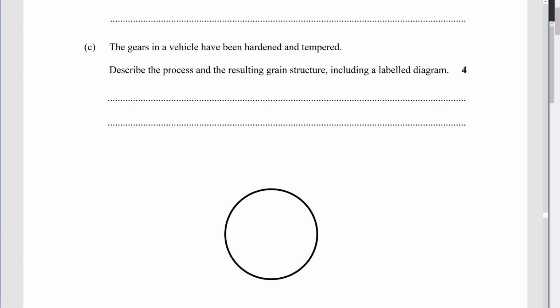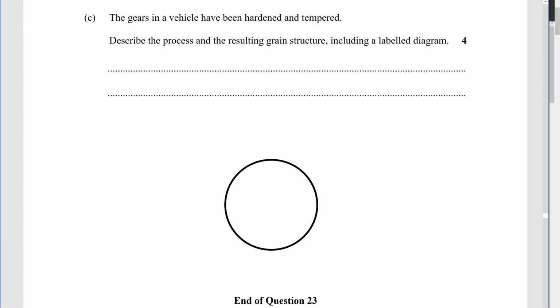Now, when I've had this question in the past, people have said, what's the difference between tempered... Oh, I said tempering. Oh, I only talked about the hardening process. I didn't talk about the tempering process. I would have lost marks there. Okay, for 2 marks, heat to 100% austenite, then quench rapidly in oil, then reheat again at a lower temperature. I'm going to add for some amount of time, but just a lower temperature, right? That's all you need to write.